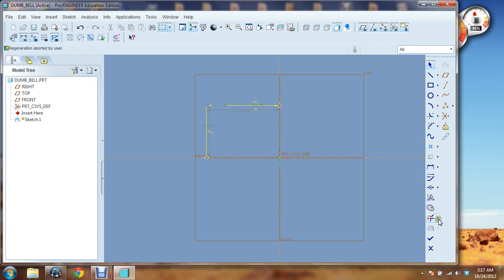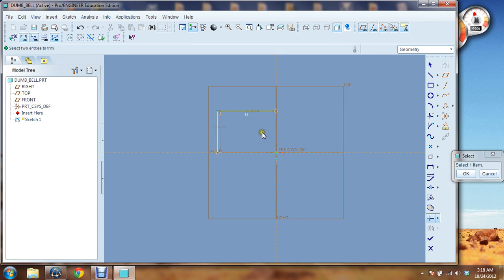And what we're actually going to do is come down here to this other toolbar. We have an option for trimming, deleting segments. We can corner, which is what we're fixing to do, or we try to connect these two lines, or we can break a line. Now what we're going to do is corner, click this line, click a vertical line, and now they are connected. Now we can move it around.